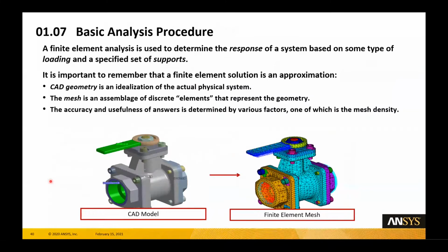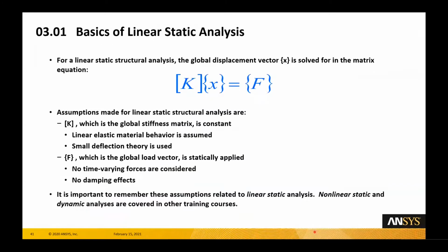So when it comes to the finite element process, normally we've got some sort of CAD geometry of some sort of idealized system. We're going to then prepare that geometry. That's what we're going to be focusing on today, and we're talking about why it's important to prepare the geometry. We can then create a mesh on our component as well, so we'll be talking in a little more detail about that tomorrow. And then from there, we can apply the analysis depending on our boundary conditions to understand what the forces, the stresses and strains might actually be.